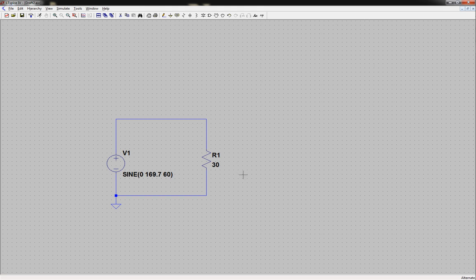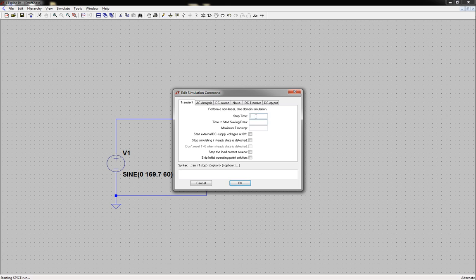So now we've got the sine, and if we click run, of course it's going to ask us for a time step. We'll do 100 milliseconds. That'll be about good. Pretty much the period, at least for 60 hertz, is about 16 milliseconds, roughly. You just have to think about your sine wave and whatnot.